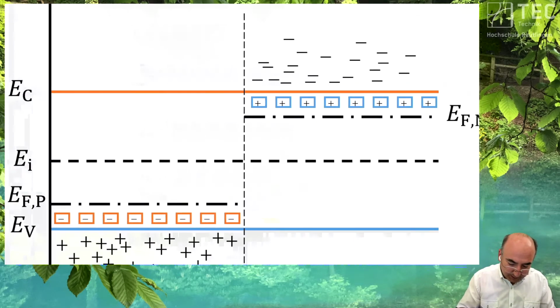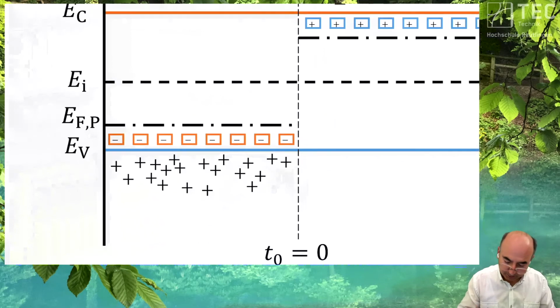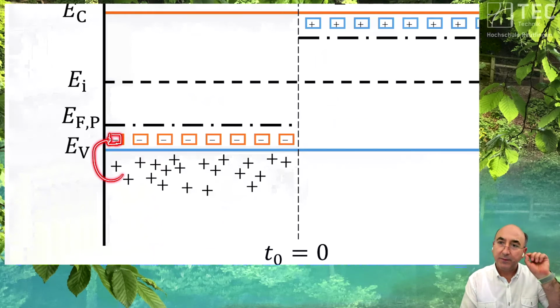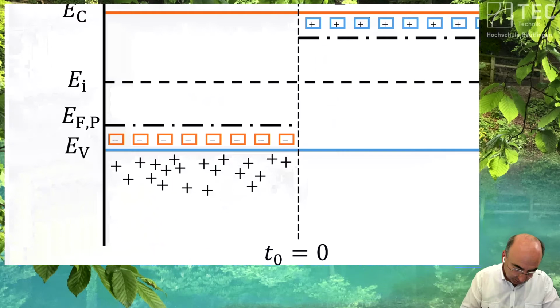Okay. The same game we have now here, but with the opposite sign. Here we have the boron, which has at the beginning 3 valence electrons. It has stolen 1 electron and is now fixed, bound to the lattice, 1 times negative. It has its noble gas configuration. And now you have here a lot of movable carriers, free carriers, the holes. Again, we are not in equilibrium.